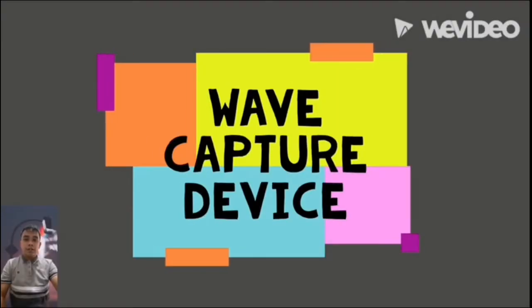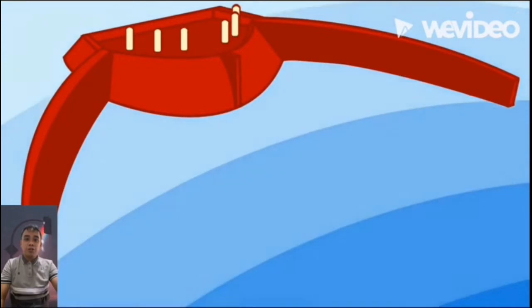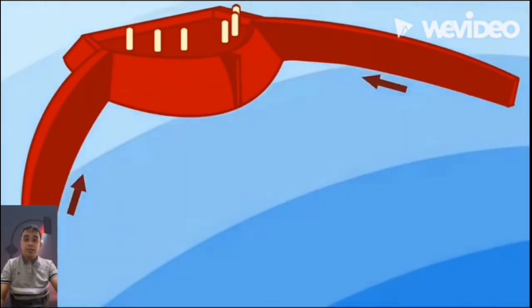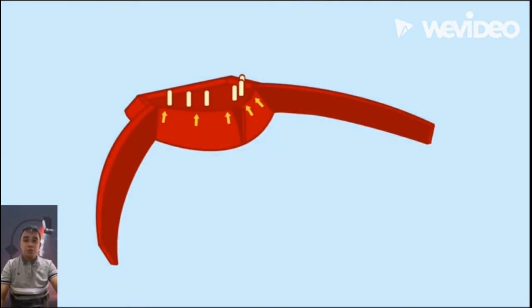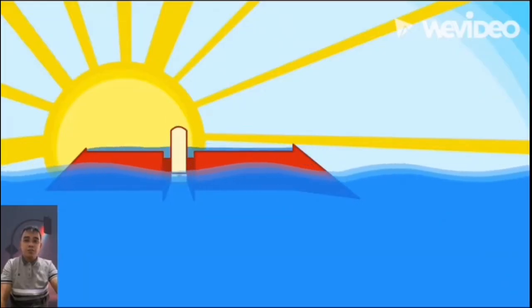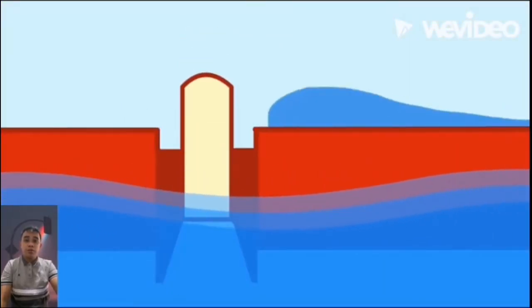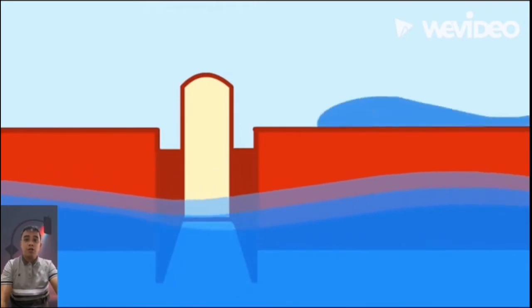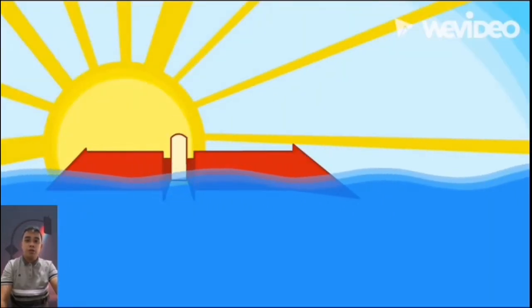The third device that harnesses wave energy or wave power is the wave capture device or overtopping power device. It's a shoreline to near-shore wave energy device that captures the movements of tides and waves and converts them into potential energy. Wave energy is converted into potential energy by lifting the water up onto a higher level. The wave capture device, or more commonly, an overtopping device, elevates ocean waves to a holding reservoir above sea level.